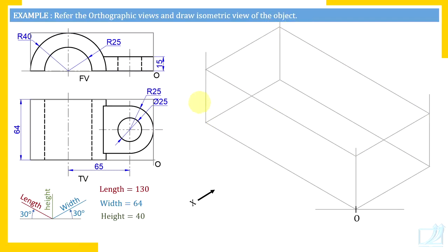Now identify parts. So there is a semi-cylinder, in fact it is a hollow semi-cylinder, but initially don't worry about holes and slots. There is a semi-cylinder and there is a U-shaped plate. This strip here suggests that there is a plate, and the largest surface of this plate is appearing in the top view, and it is a U-shaped plate.